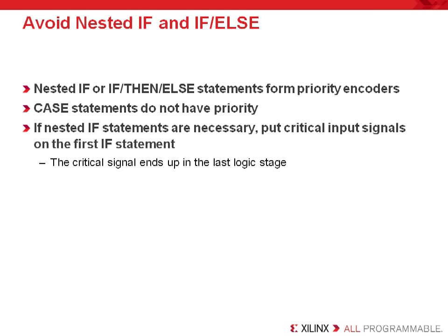Now, if you build with nested if-then statements, be sure and watch your timing on your inputs because the LUTs can cascade easily. Always be sure in this case to put the timing critical signals first in your HDL. However, the best solution is to build the component with a case statement as much as possible. Case statements do not build with LUTs in series and tend to build the LUTs in parallel, which is dramatically reducing the number of logic levels.